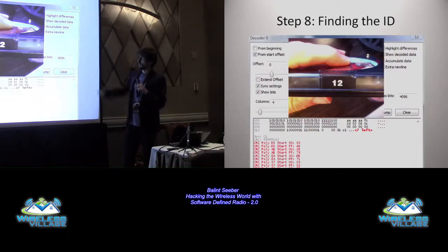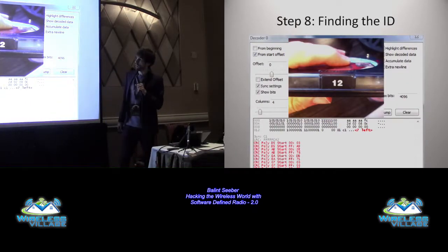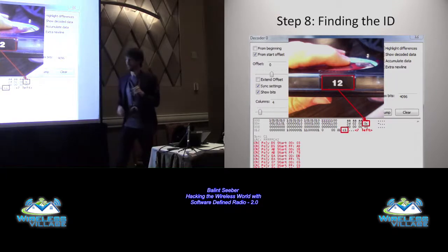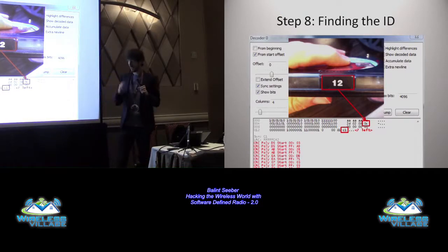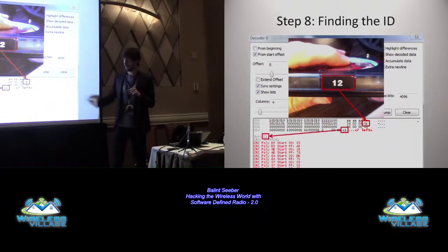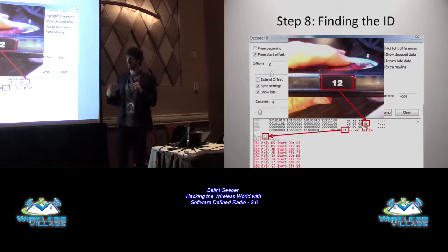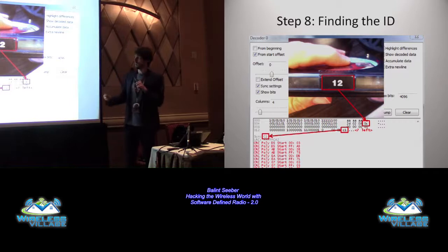And now, once you actually get a pager, you check the ID, and then you look in your Manchester decoded stream and think, oh, hang on, what do you know? There it is. There's also this odd byte at the end that was changing, as you saw before. That's the checksum. You can go through and try a whole bunch of different CRC algorithms. Turned out it wasn't actually CRC, it was really simple. You add up your bytes and you mod 255. It's a very simple check, and that matches, as you can see there. So that's pretty much the packet format.